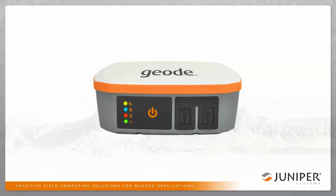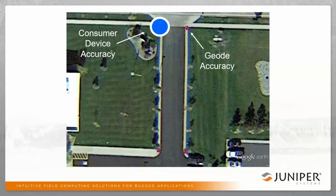And you're now, instead of a 2 to 5 meter accuracy, you're down to about 12 to 15 inch accuracy with the Geode. And I'll show you a little bit of a demonstration here on how that accuracy works. So think of it like a circle, a consumer device, like a typical tablet, or the GPS that's on the Mesa 3. If you mark a point, then think of a 2 to 5 meter circle. So once you get back to the office and look at your point, a lot of times it'll be close to the middle, but there's chances that it can be anywhere within that 2 to 5 meter circle.